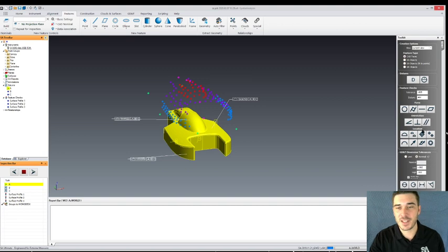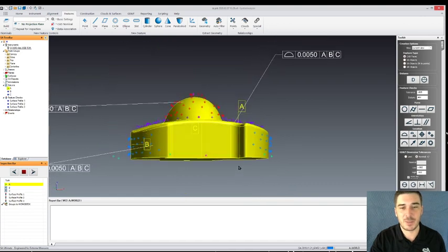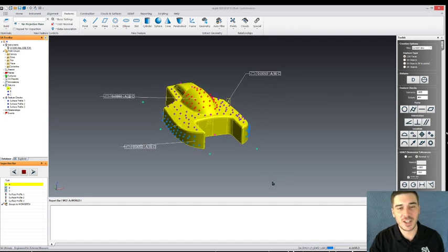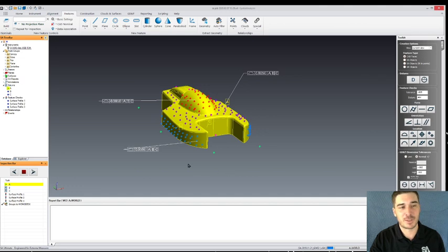And I don't know if you can see this window. It's on top. It's just our Relationship Minimize dialog. So I'm going to run optimization. And SA was able to solve it with a really good fit. 1 thou and 3/10 was our RMS on that. But now our data is fit to our CAD model, and we're ready to go and filter out this data to the appropriate checks and surface profiles.